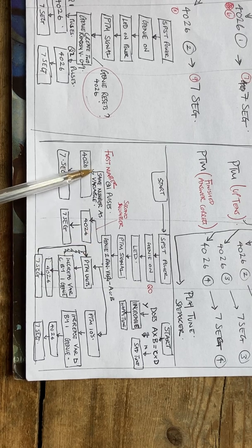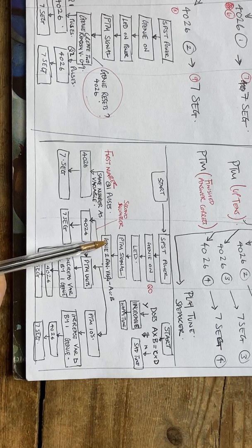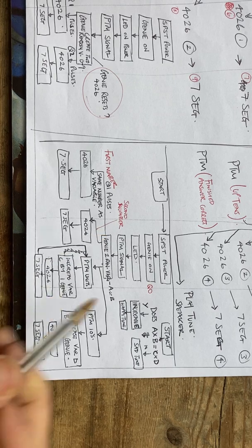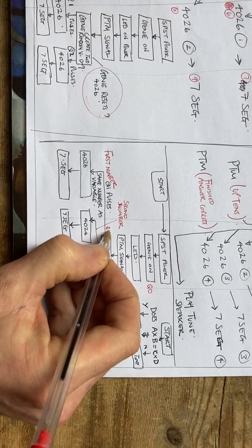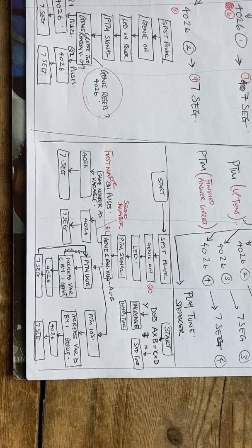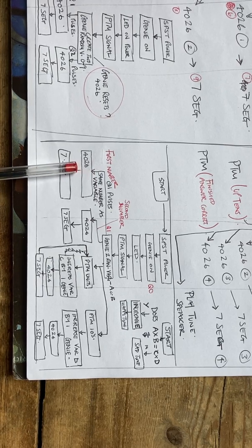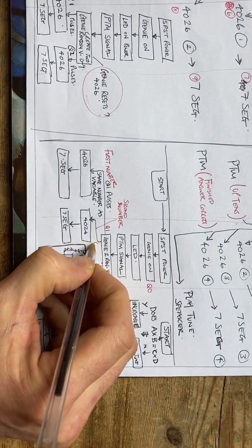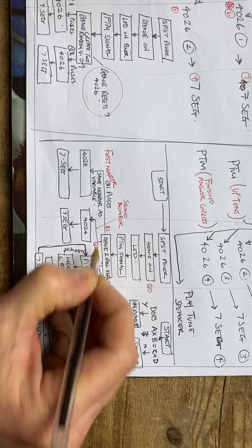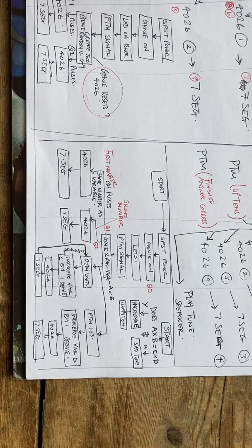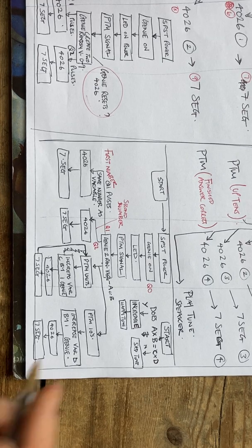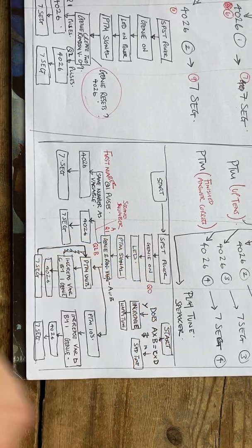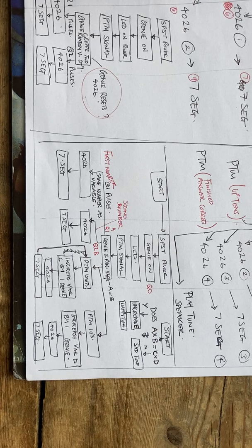So we go over here. If the first one is 8, for example, the first random variable, so A equals 8, then output, let's call that Q1, Q1 will pulse 8 times. That will be interpreted by the 4026, and the configuration on that 7-segment display will be 8. We've got the second one here, and that's going to come out of Q2. So Q2 does exactly the same for the second variable. And I'm going to put down there A, and I'm going to put down there B, so we know what variables these refer to.